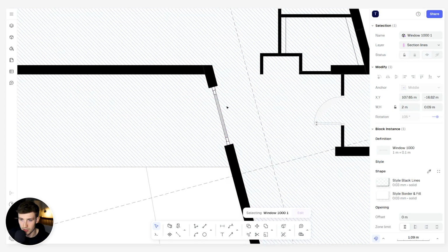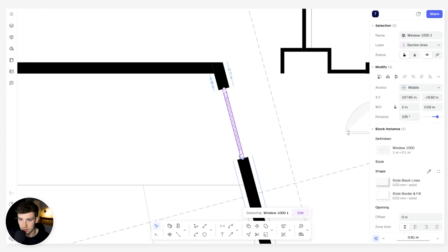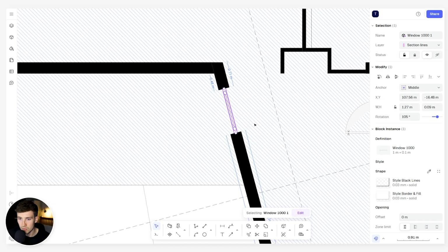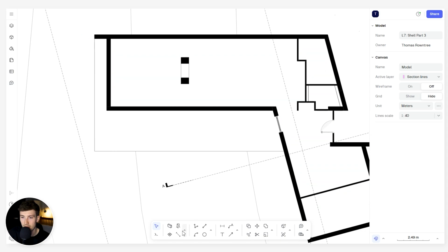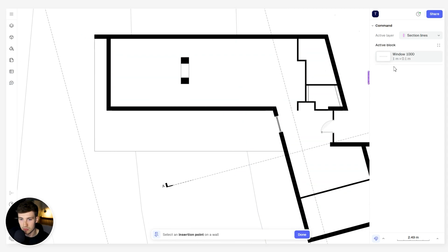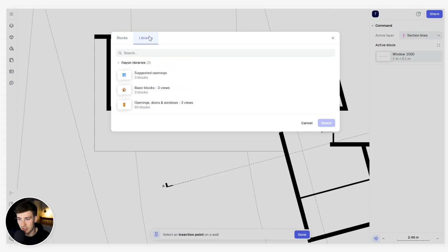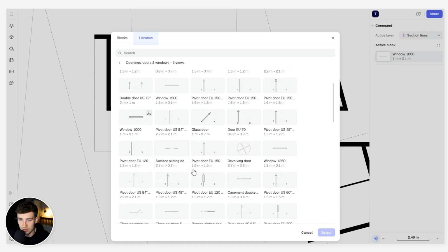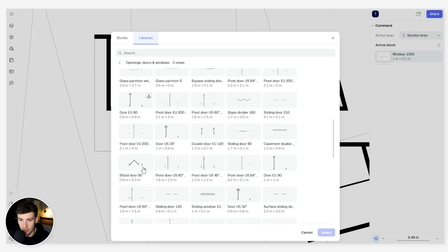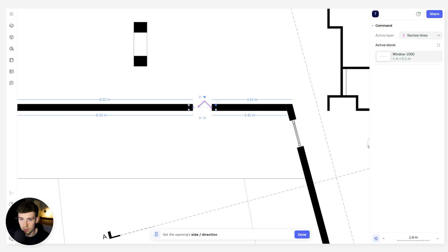And the idea is that as you enter this space, you've got this point of arrival. And maybe it just needs to be a touch smaller. It doesn't need to be so thick. And this is going to be a case of me populating the drawings with these openings. You can begin to place different types of doors, bifold doors ideally in this zone here, because we have this access between the dining, kitchen and living room, and we want that access into, so for example, let's do a bifold door. We'll place that into the model, and if we want to do multiple of them, we can select them in.